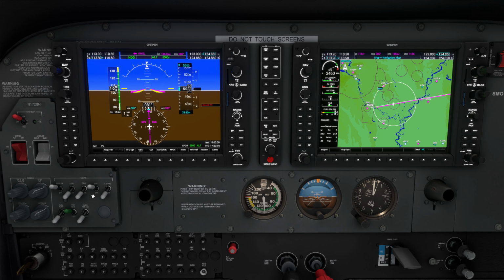So our procedure is to turn off everything we don't need. So I'm going to go ahead and turn off the nav lights. It's an emergency. You can see the discharge goes down a little bit. I'm going to turn off the beacon, and it goes down a little bit more. Well, it won't let me turn the beacon off for some reason, but I would. If I'm not in icing conditions, I can turn that pitot heat off, and you can see the discharge drops a little more, but we are starting to lose voltage already. It was 24.4, now it's 24.3.